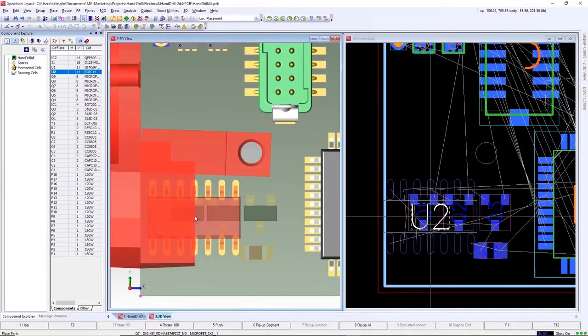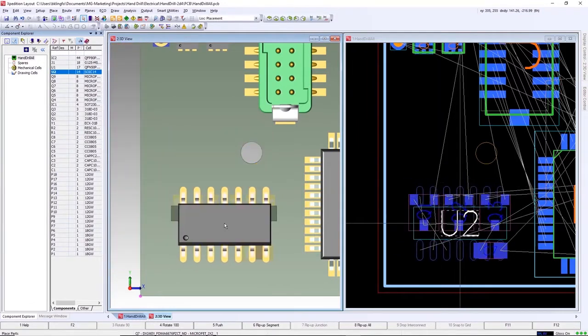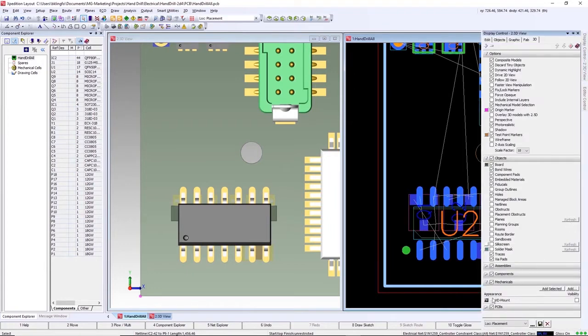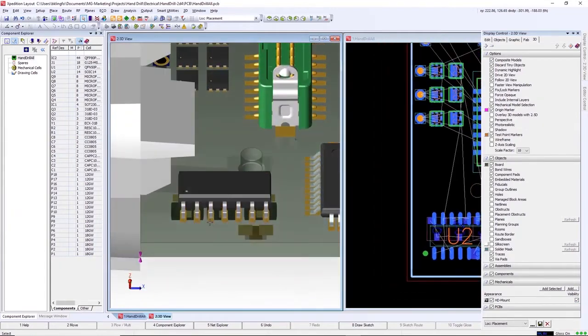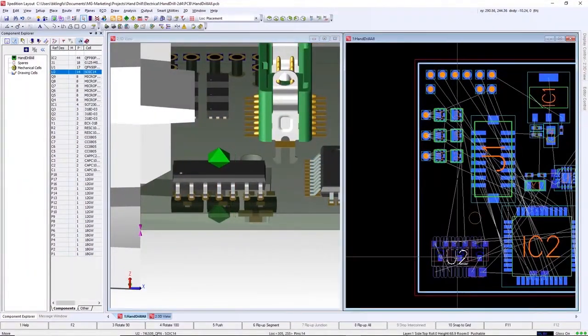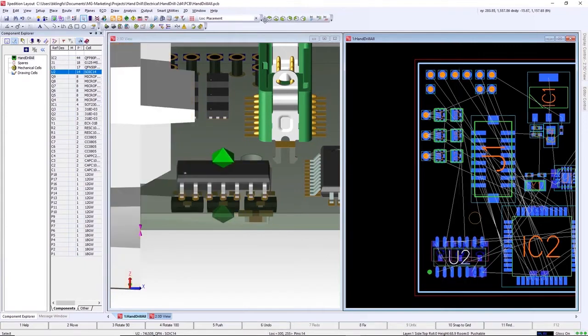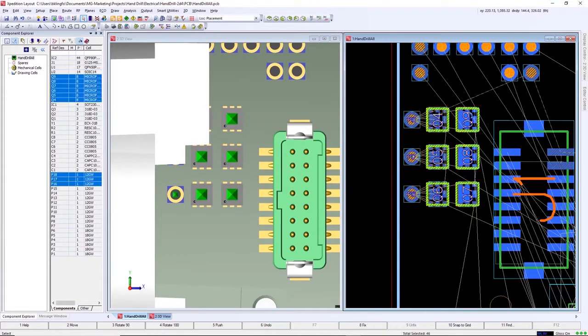Pulling an IC from the component navigator and placing in the lower left corner, we'll notice the PCB heatsink becomes visible in red, showing a collision between these 2 objects based on our design rules. As we move the part further away, the heatsink turns yellow, showing it below the optimum rule but more than the minimum. The heatsink was left invisible on purpose to help with placement. Making visible again shows placement would have been difficult from the top view. To fine-tune placement, we can move the part in 2D while viewing placement in DRCs in 3D.